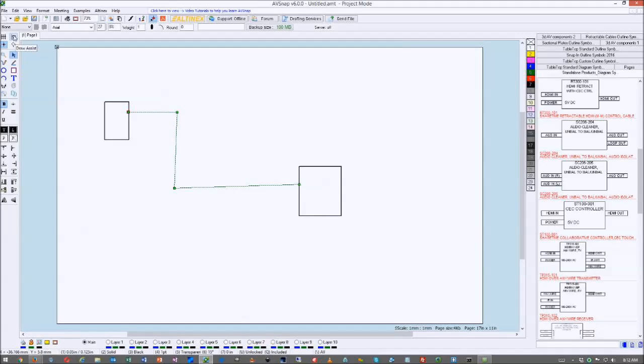The draw assist feature is right here. You can see there's 90 degrees. Once you turn it on, as you can see, it tells you where this line is going to snap. So if I let it go, it will snap to the top. If I select here and bring it outside, it will snap to the side. So you can see it automatically adjusts the right angles when you adjust the lines. You can also grab it on the center and move it from left to right, or grab it here and move it up and down. So that's what we call draw assist. Very powerful system, and you'll see when you connect multiple lines, it becomes very easy to do this.